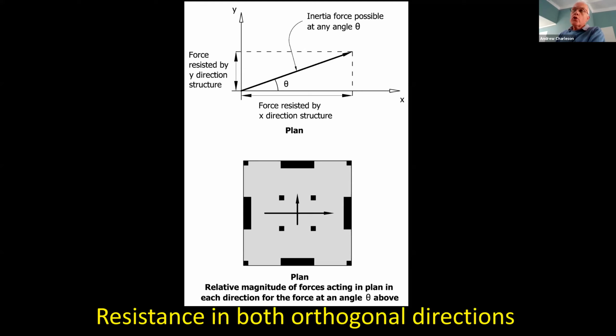And so when it comes to your building, you can superimpose on your building plan an x-axis and a y-axis, and then make sure you have strength in those 2 directions. And then you are applying the first principle of earthquake-safe design.